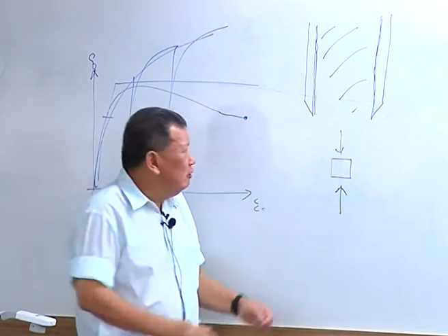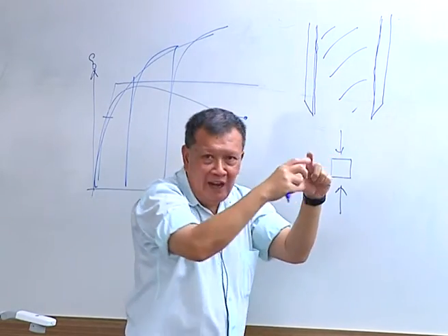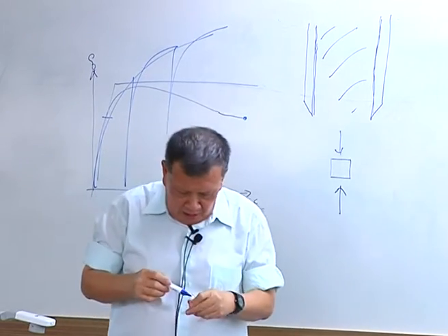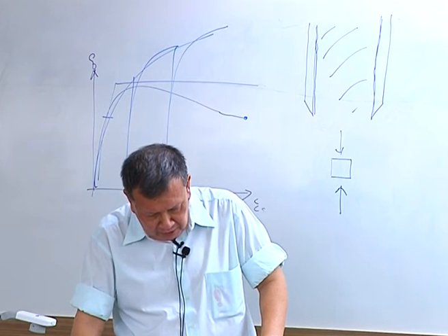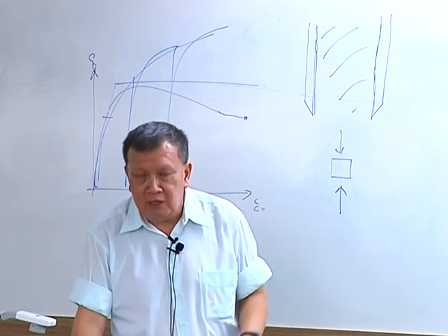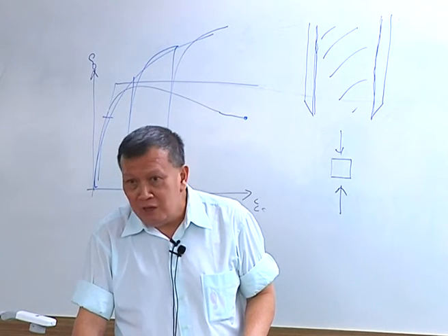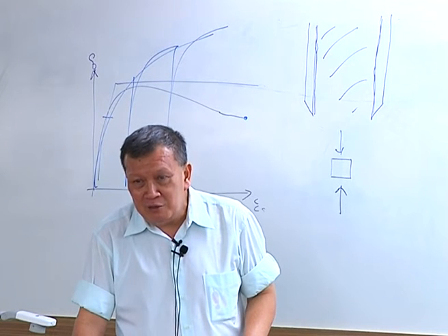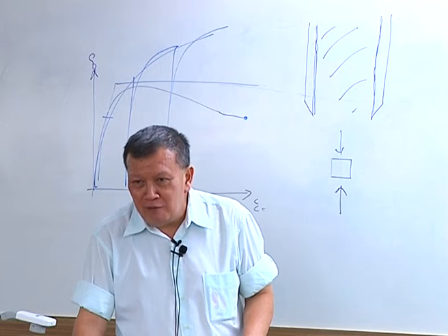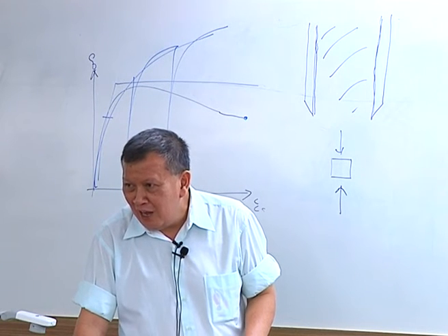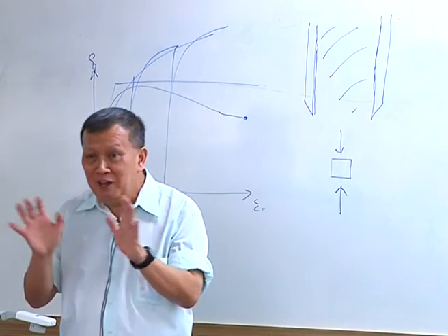Alright? And then when you push it in, when this guy got into the tube, it probably started to relax a bit. So basically, Clayton and, I can't remember the paper by Clayton and somebody in Geotechnical, when they look at this problem, what they say is that you actually put the soil through one cycle of triaxial compression before it even got into the sampling tube. That's why I always have this joke to tell: an undisturbed sample is a very heavily disturbed sample. A disturbed sample is a completely destroyed sample. In soil, that's the way it works, alright?